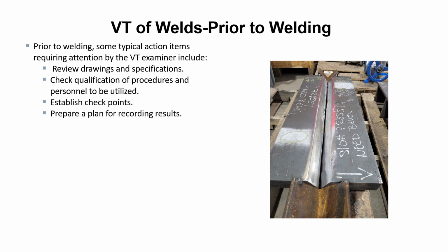You want to establish checkpoints. When do I want to look at this? How much of this needs to be welded up before the welder comes and gets me and I take a look at it again? So I probably want to see his fit up. All right, let me see before you start welding. I want to see your first pass. Then I'm going to come back in 3 or 4 passes, depending on how thick it is. And then I'm going to look at the cap pass, the last pass you put on.